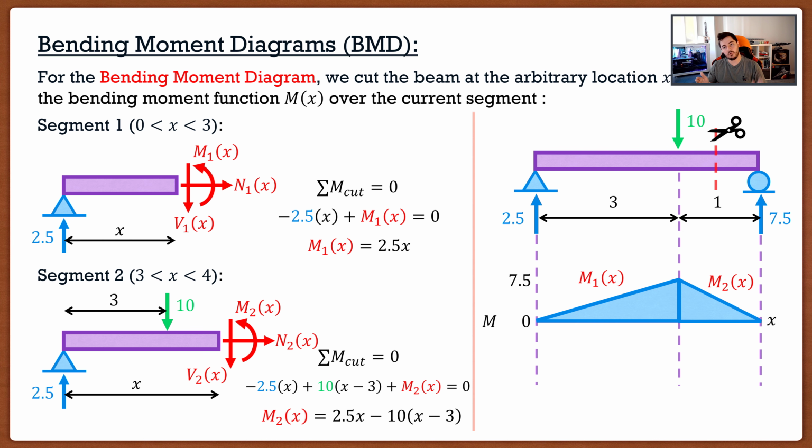Of course, the support reactions will pop up, but they always end at 0. If we had a concentrated moment, like a fixed support, that'll also pop up, but they should always start and end at 0. There's the first thing.